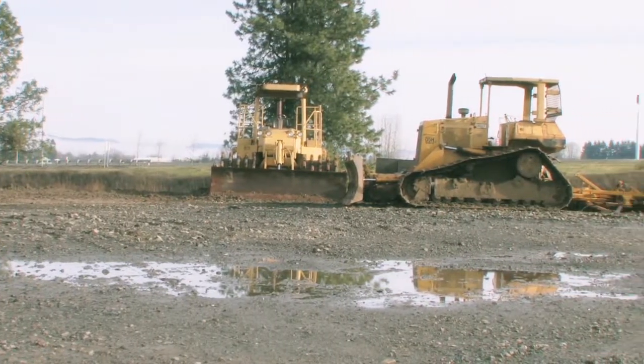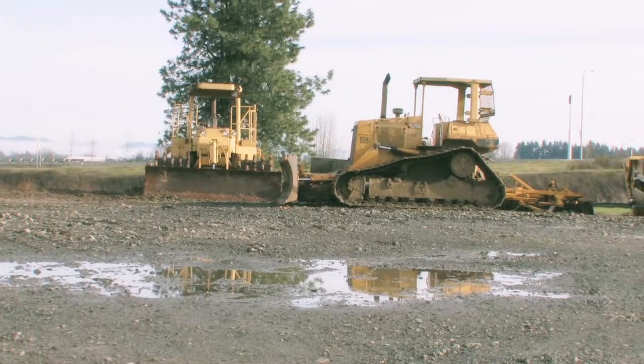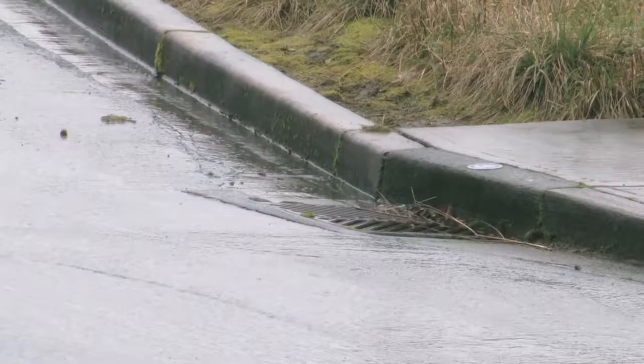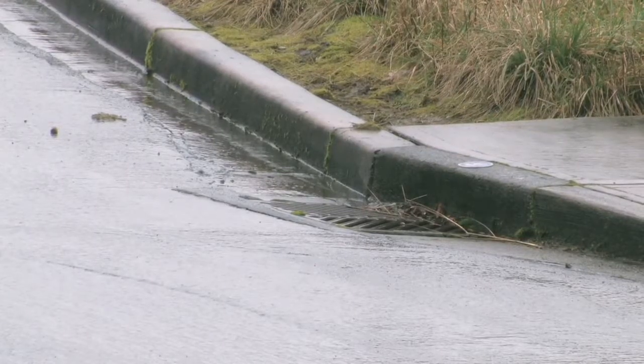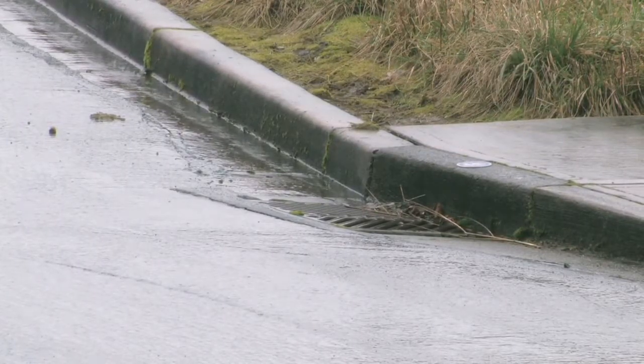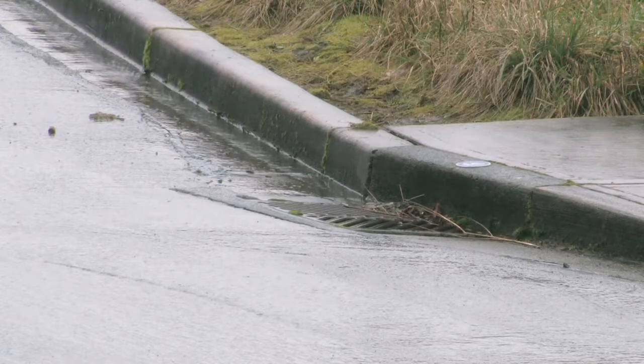Conventional rainwater design strategies typically involve getting the water off the surface as quickly as possible, getting it out of the way and putting it underground. And that works well as far as getting it off the surface, but now it's underground and we still have to deal with it. We still have a lot of runoff volume, it's still moving quickly, and it still has those pollutants in it as well. So now we have to move that water somewhere as well. So we have to build a very large and sometimes complicated drainage system underground in order to convey it where we need it to go. Also, quite often when we build a system, it can do one thing.